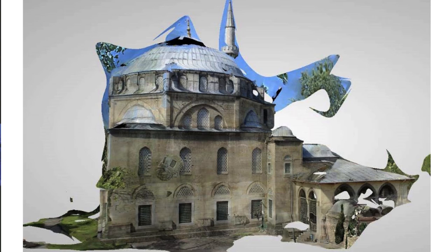One of the biggest drawbacks we found is simply the size of the files and the number of photographs that you can reasonably upload. For us, working in the field, I think we had a total of 238 images to create just the musalla, the prayer hall. It took about 2 hours to upload because we had a very slow internet connection. But then we were able to process it on the cloud. So we came back in 6 hours, and we had the basic geometry and the basic model created. It did take about 20 hours of post-processing back at the lab to get it into the state that you saw there, that Chris was zooming in and out of.